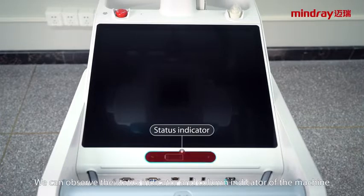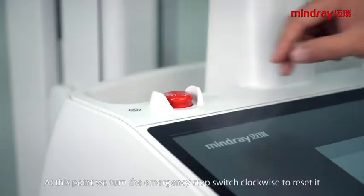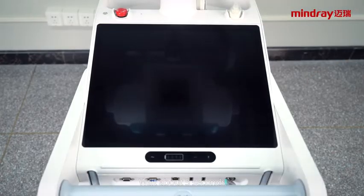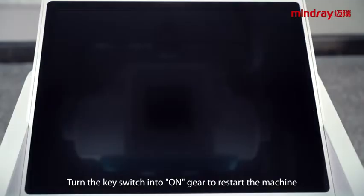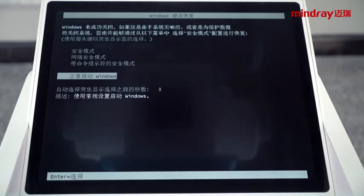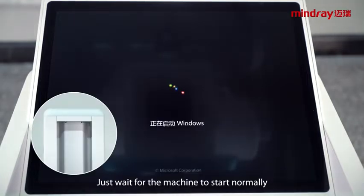We can observe the status indicator and the column indicator of the machine. When you see the light completely off, it means that the forced power shutdown is successful. At this point, we turn the emergency stop switch clockwise to reset it. Wait about 5 seconds. Turn the key switch into the on gear to restart the machine. At this time, the screen will show an abnormal shutdown prompt screen. This is a normal phenomenon. Just wait for the machine to start normally.